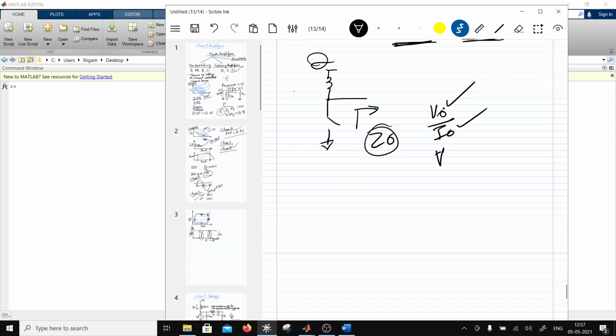Then you take the second and the third harmonics, right? So second harmonic, and you will find the second harmonic impedance. So if you have a waveform and you have a Fourier expansion of that waveform, you can take the coefficients and take their ratios. You'll get the fundamental impedance, the second harmonic impedance, you can even get the third harmonic impedance, right?